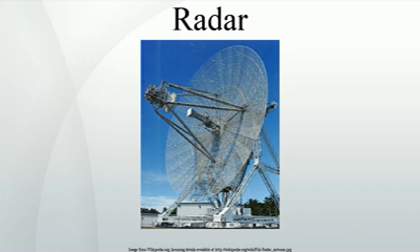Antenna design. Radio signals broadcast from a single antenna will spread out in all directions, and likewise a single antenna will receive signals equally from all directions. This leaves the radar with the problem of deciding where the target object is located.